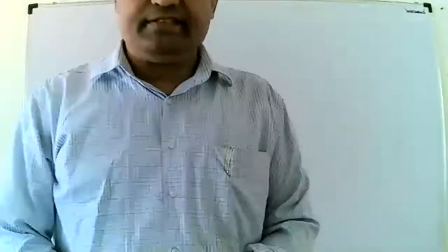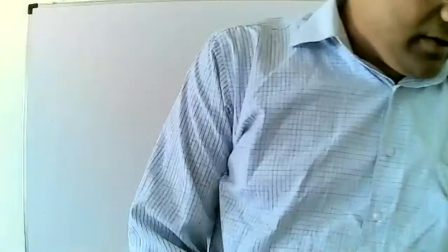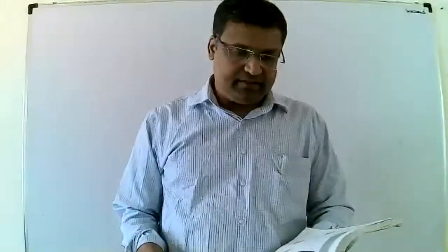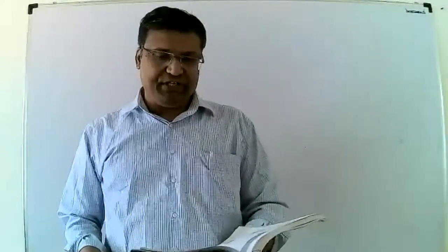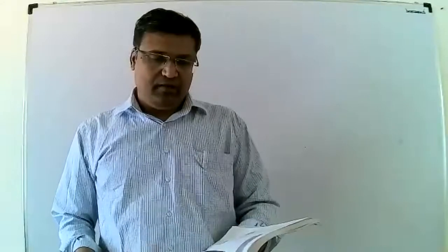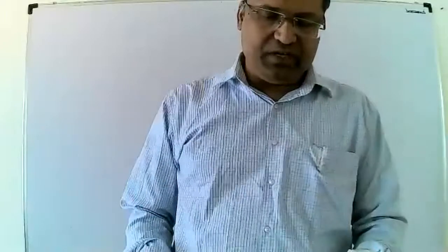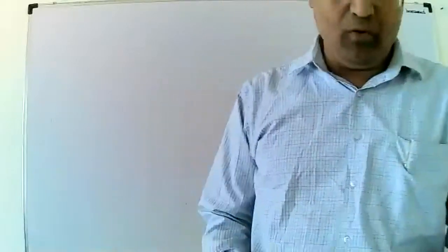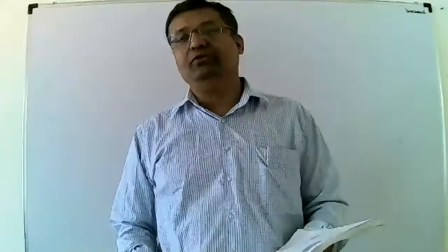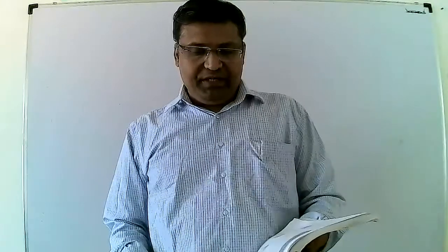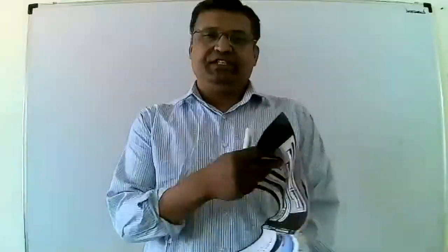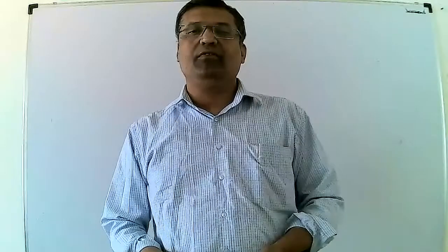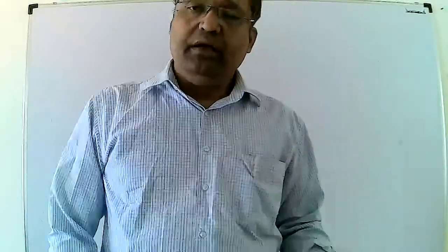Here, the same problem I will take. A beam section 100 mm by 200 mm is subjected to a shear force of 60 kilonewton. Determine the shear stresses induced on a layer at 50 mm above the neutral axis and 25 mm below the neutral axis. Here, the beam is a rectangular section, which is given in rectangular form.